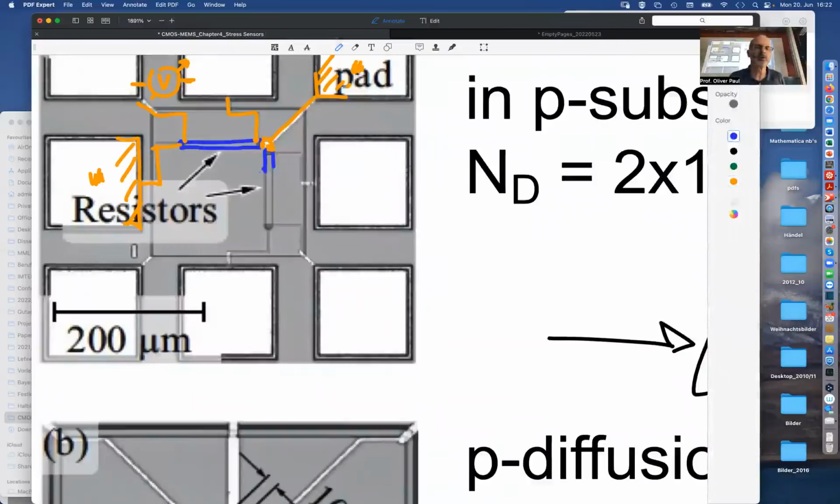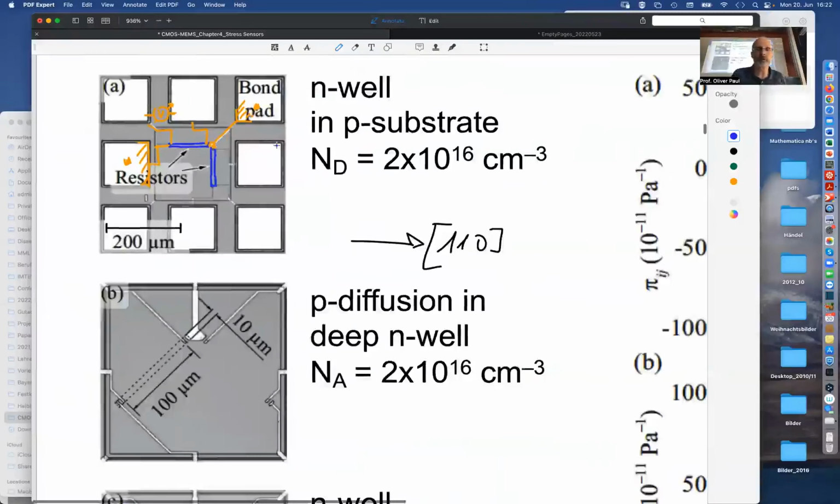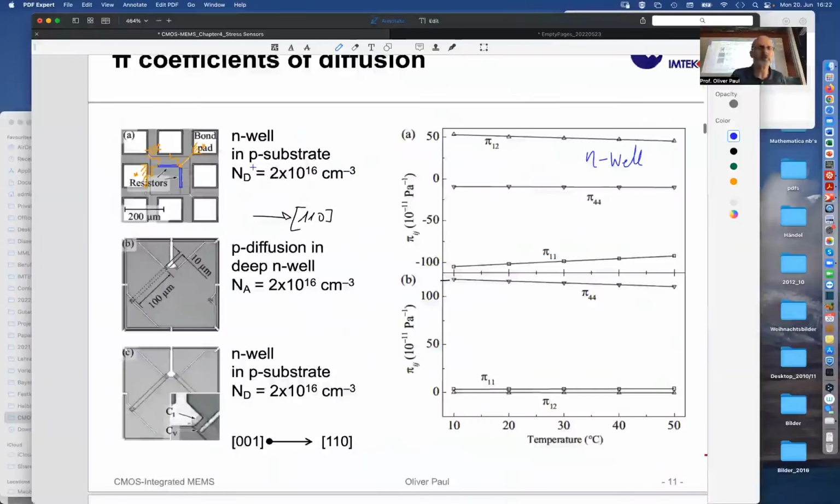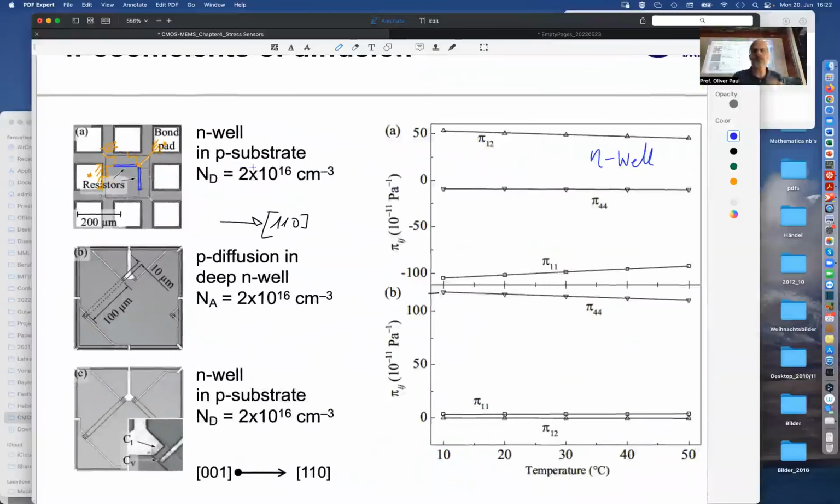There are two half bridges, and you get the information out here that you get out from a full bridge, but a full bridge is of course more complicated, and so we can measure some things here. And from the full bridge, you don't get necessarily also the temperature dependence, so it's good to look at half bridges. And then the values that came out here at 30 degrees, let's say something like room temperature, are slightly smaller than what was tabulated by Smith.